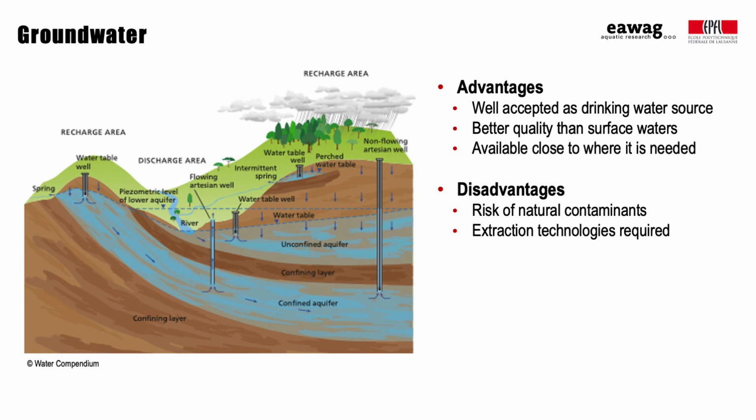Further, abstracting groundwater from a well at rates exceeding the recharge rate may decrease the level of the water table. The well may eventually run dry, and this may also increase the potential for drawing contaminants or salt water into the aquifer.